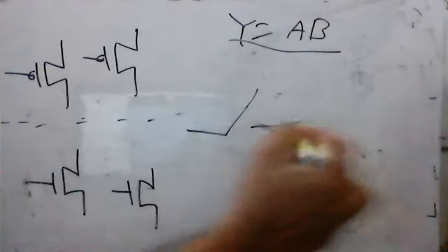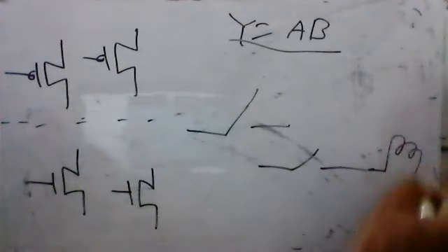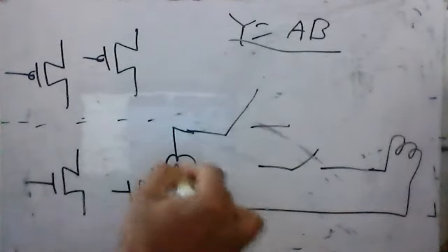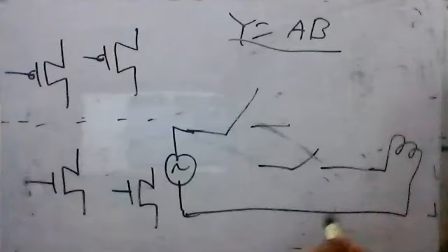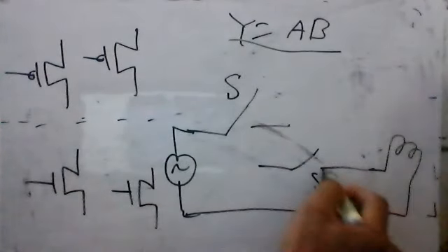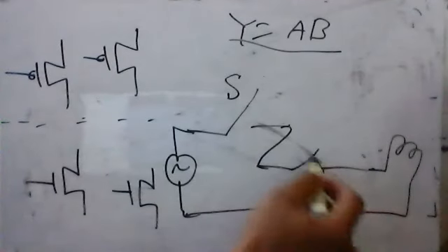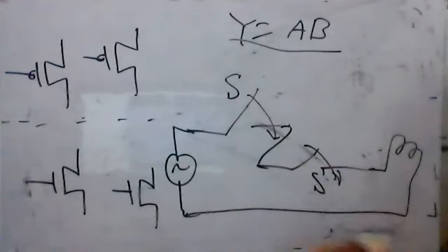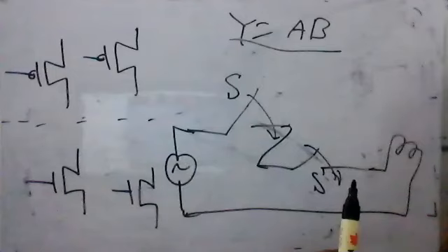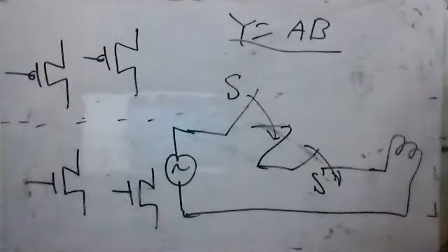তাহলে আর একটু দেখো, তোমরা এই যে সার্কিট 1-এ দুইটা সুইচ কানেক্ট করেছো, একটা সুইচ আর একটা সুইচ, এই দুটো কানেক্ট করে তুমি একটা ল্যাম্প জ্বালাতে চাও, এটা তোমার পাওয়ার সাপ্লাই। তাহলে এটা অ্যান্ড গেট তৈরি করবে কি করে? এই দুটো সুইচ সিরিজে দেবে না প্যারালালে দেবে? স্যার সিরিজে কানেক্ট করতে হবে। সিরিজ, রাইট, গুড। সিরিজে দিলে অ্যান্ড হয়। অ্যান্ড হলে বোথ মাস্ট বি টার্ন অন। দুটোই অন না করলে জ্বলবে না। আর যদি তুমি অর গেট করো, তাহলে ইট উইল বি প্যারালাল। অর গেটের সময় প্যারালাল, তাহলে অ্যান্ড গেটের সময় দুটো সিরিজে হয়। সো আমাদের সেটাই নিতে হবে.